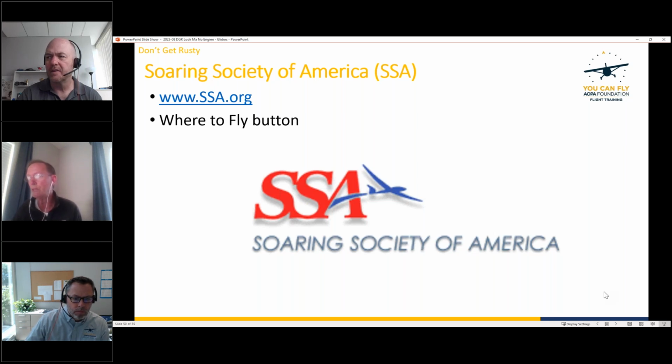In that circumstance you need to establish a letter of agreement with the local air traffic control to create what's called a wave window, where they will literally take out a chunk of space above 18,000 feet, allow gliders to fly into it, and fly everything else around it. They'll make sure that nothing's in that airspace with you.